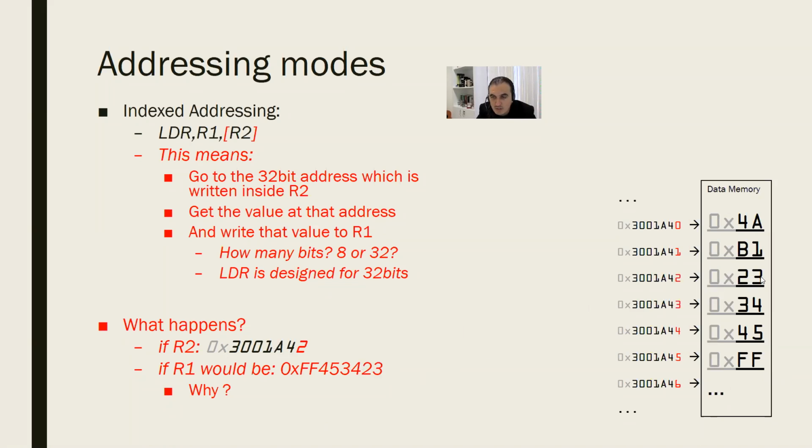So at the lowest address, I have this byte. Next, the next byte. And at the highest address, starting from these addresses, counting 4 address values, I had the most significant byte. So this was all about this index addressing operation of more than 1 byte, which makes a summary of a lot of things. Instructions being 1 byte, 2 byte, or 4 bytes. In other words, 8-bit operations, 16-bit operations, or 32-bit operations. They are by definition like that.